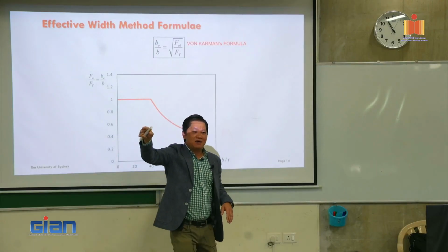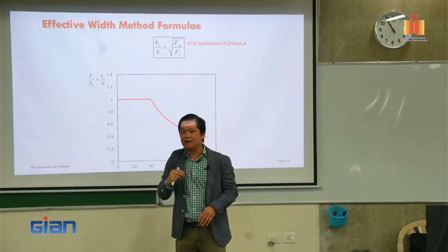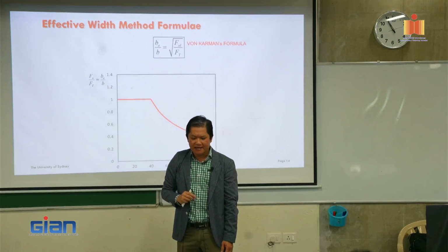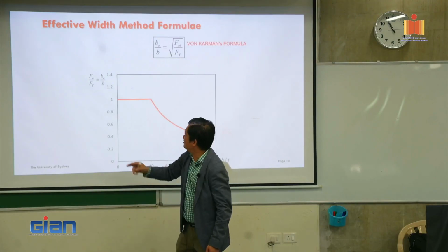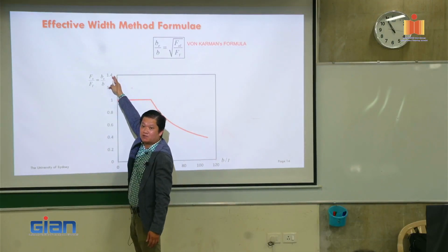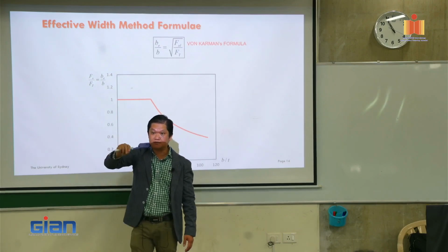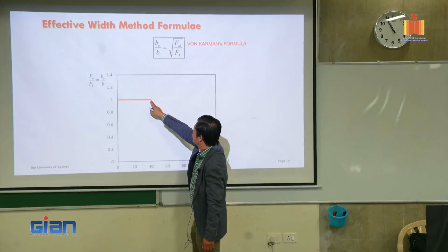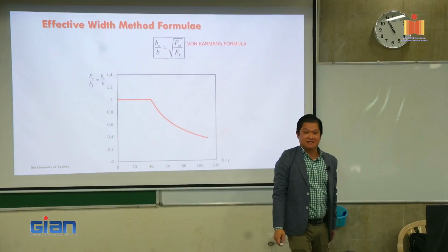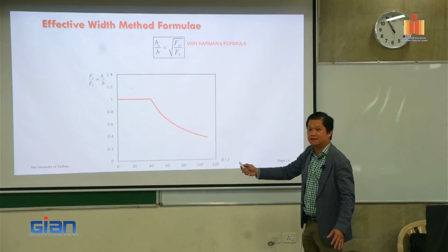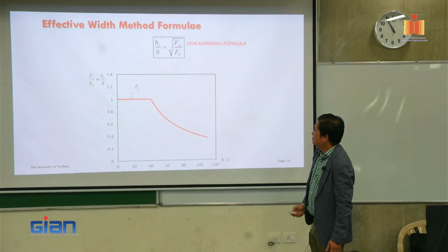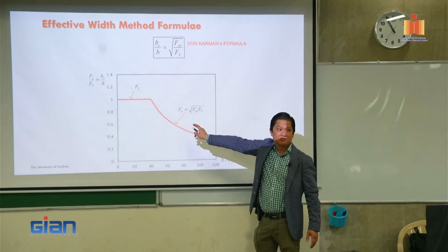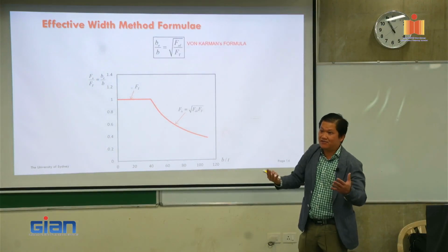In some codes now, particularly for cold formed steel, based on the work of Professor Schafer, they introduced the inelastic reserve. So actually it's not 1 here, it goes up, about 1.4, 1.3, to take that into account. We can talk about that later, okay. Right, so this is Fy cut in, and this is the von Karman equation. It takes into account the post-buckling. That is Fy, and that is his equation, right? So in theory, that looks good.